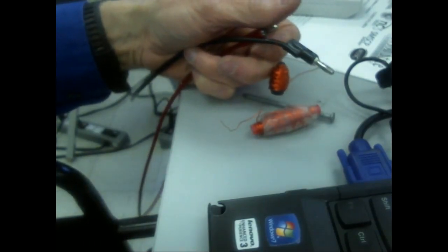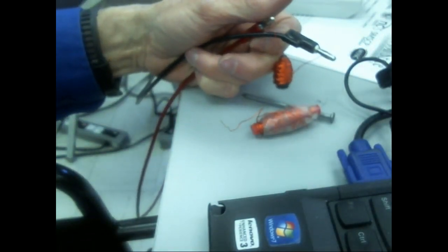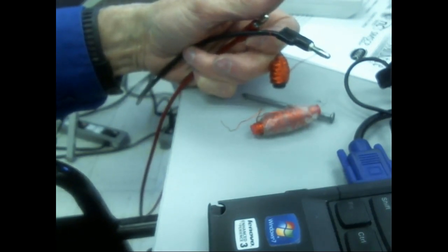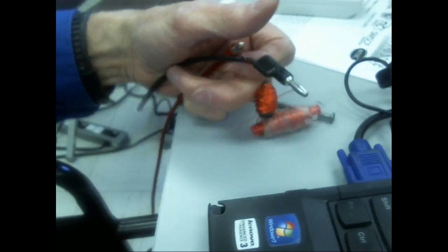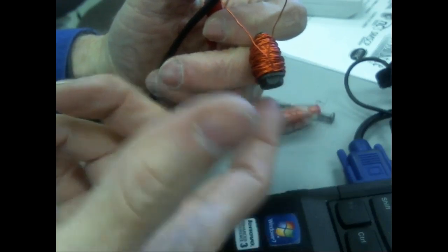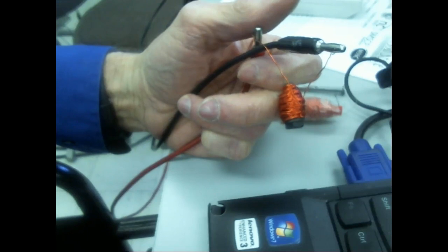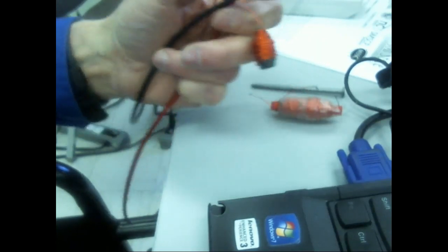And not only that, I can vary the strength of the magnet by changing the amount of push I have into that. So I can control it by the amount of push I put on. So the bigger the voltage, the more field we can generate, but you've got to be careful. The wires are conducting current, and the only thing that's limiting the current now is the resistance of this wire. So that's why you'll see these electromagnets have a lot of wire, and it's very small size wire too, to get enough resistance from the wire so it doesn't burn up, right? You understand? And this right here would get hot if I did it.